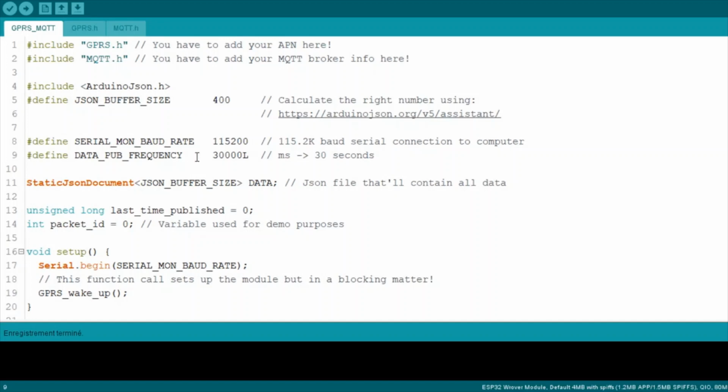So one of these steps is the preprocessor, and the preprocessor simply looks for these words in the code and replaces them with this value, even before compiling the code. That's why it doesn't eat RAM or memory, as opposed to these, which are variables that are stored in memory.